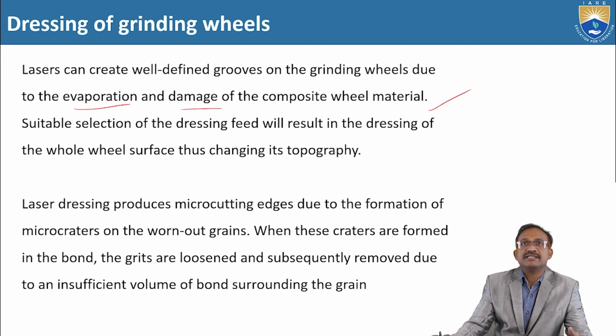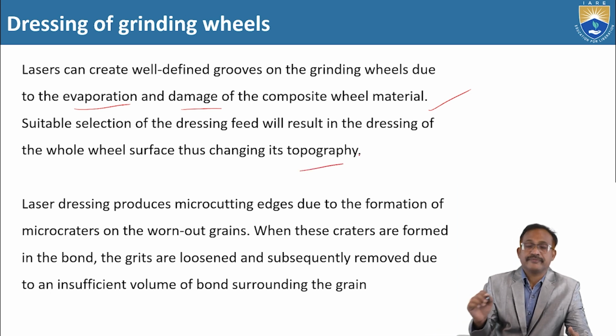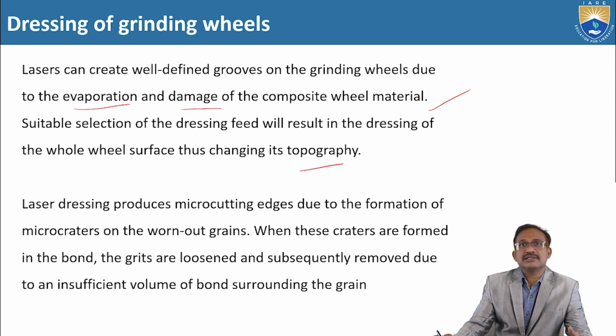Suitable selection of the dressing feed will result in the dressing of the whole wheel surface, thus changing its topography. Laser dressing produces micro-cutting edges due to the formation of micro-craters on the worn-out grains.